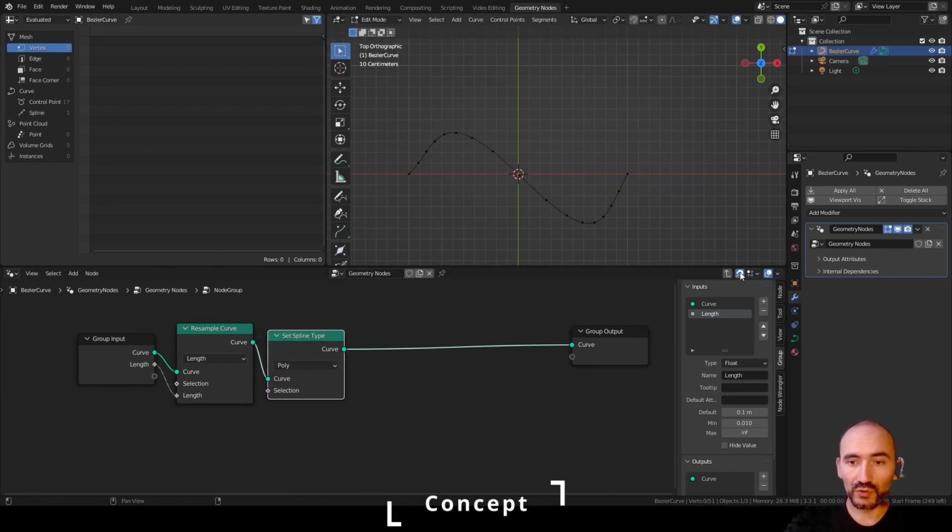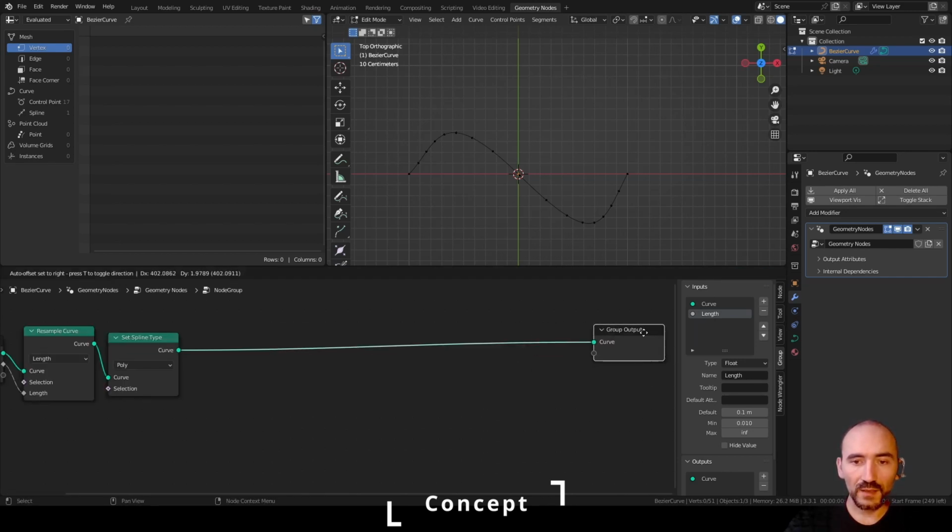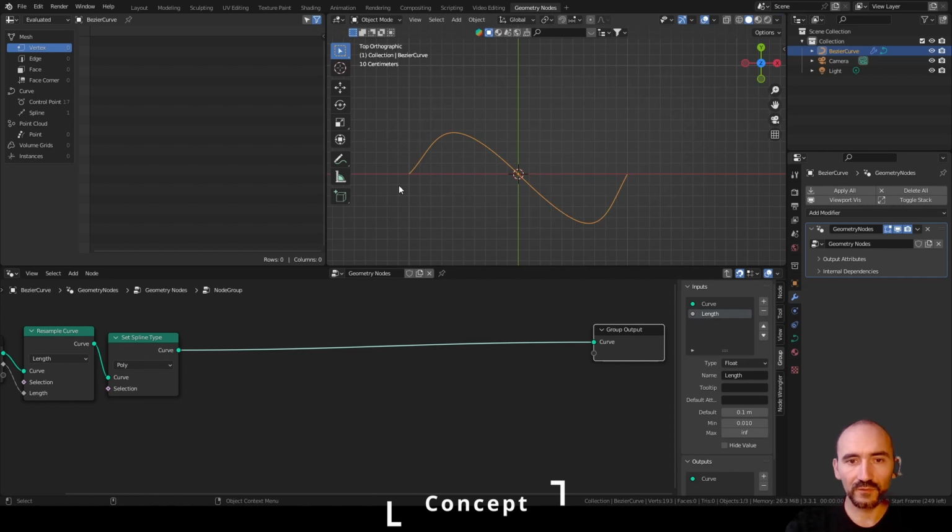Select this button to snap to the grid and then press tab to exit from the edit mode of this curve. And what we want is the ability to instance some object along the curve and to be able to scale these instances, offset these instances and filter their visibility, like so. We will add some parameters like normalized, etc.